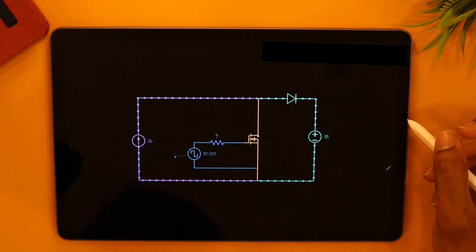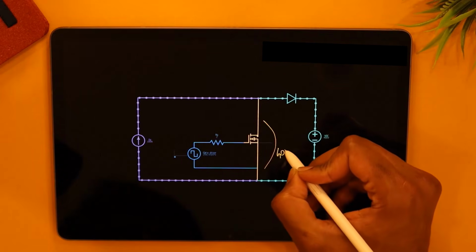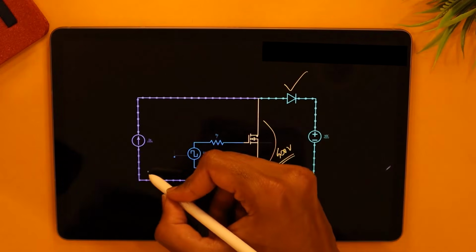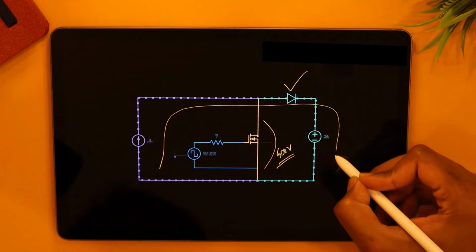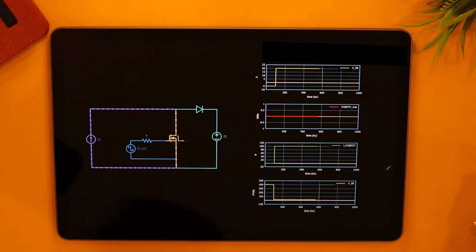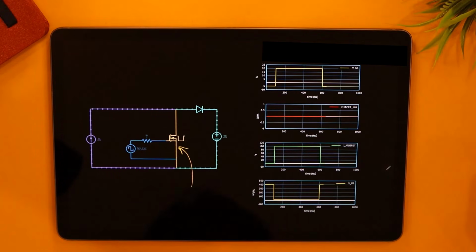When the MOSFET turns off, it develops this entire 400 volts across itself, turning this diode forward biased, and hence the input current of 100 amps flows directly to the output voltage supply of 400 volts. In a typical power converter like this one, the MOSFET is switching probably 100,000 times a second. It switches quite a bit.